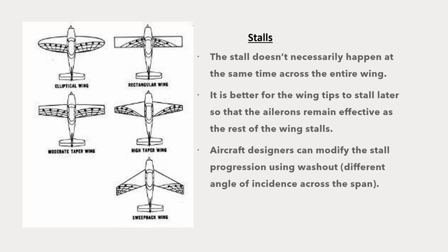The important thing for you to know as a pilot is that different aircraft designs will have very different stall behavior. When they design training gliders, they put a lot of effort into making sure that they stall in a very benign way.